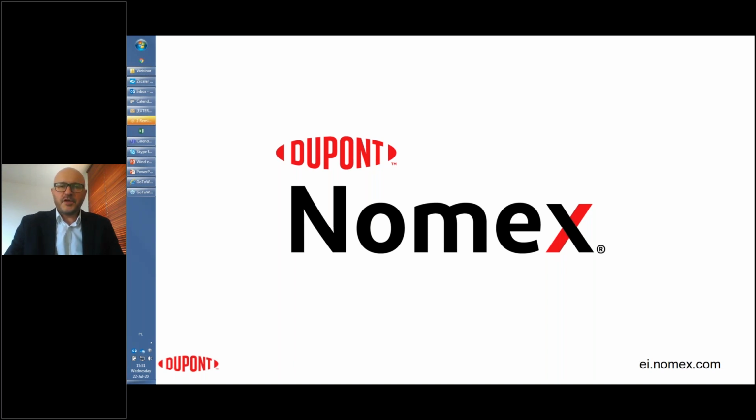In the power transformers, we talked more about hybrid designs where the Nomex insulation was combined with the cellulose. Now, with the growing interest in high temperature power transformers and the growing size of the wind turbine transformers, we are getting ready to supply this type of component. We have already commercialized the wet formable Nomex board for shaping the high voltage insulation parts.